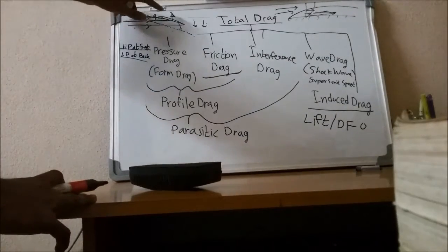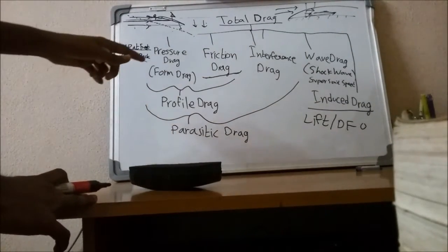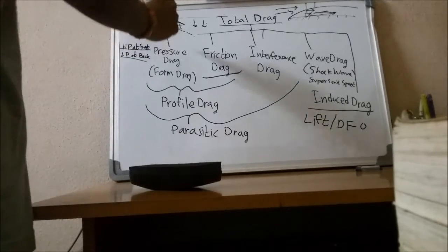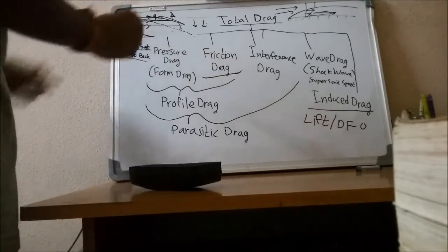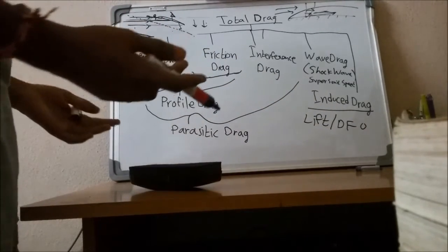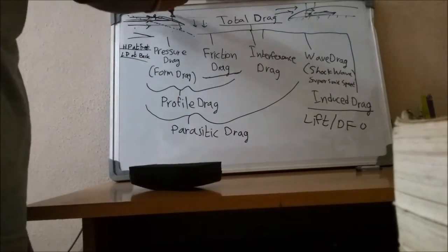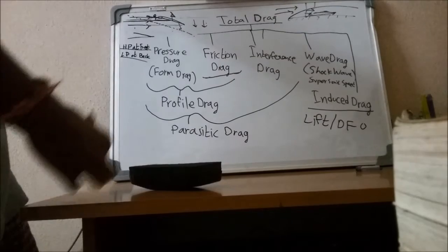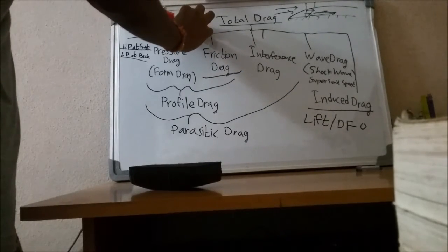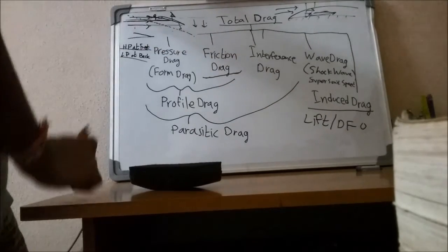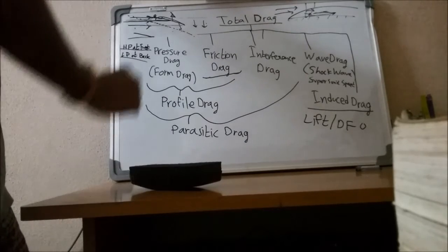So in order to compensate for the loss of lift, I think you are trying to understand, whenever there is a reduction in angle of attack, there will be loss of lift force. So to compensate for the loss of lift, we will have to put the wing at a much higher inclination.